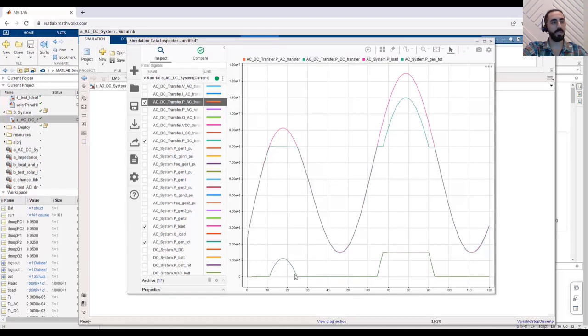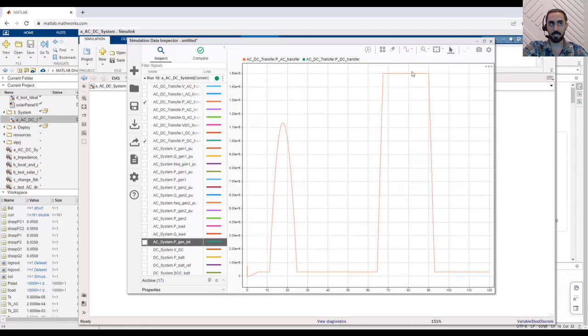We transfer the power to where the peak meets. So this is a successful operation. When it hits the limit, we start transferring. But when we reach the second peak, we have a limit of 1.5 megawatts, so we cannot provide more than that. So that's why the generator has to pick up the extra and generate over that rating value. So that means the simulation is working correctly.